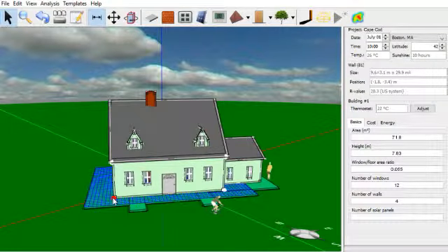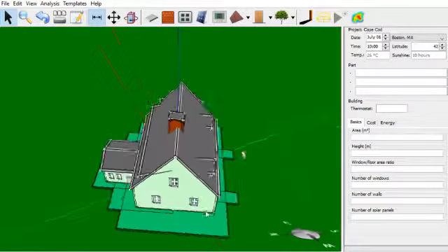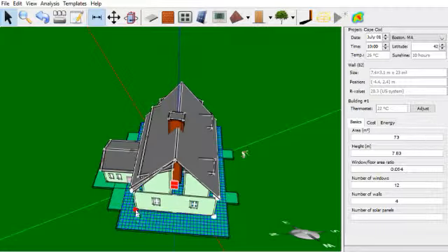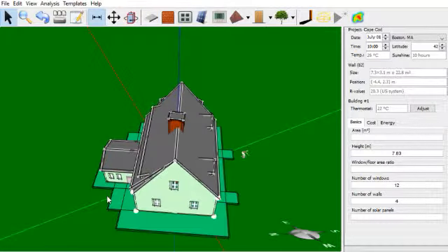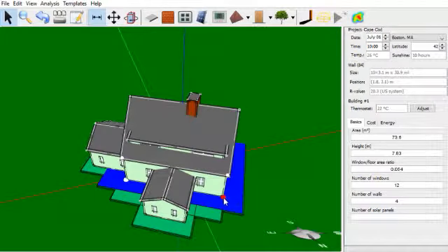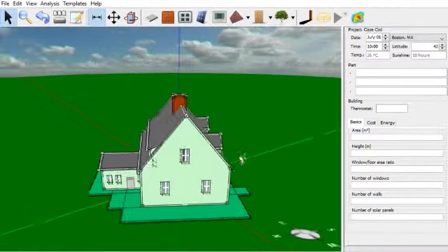However, we can adjust it to be exact by clicking on the wall and dragging the bottom circular node while holding down the Shift key to move it 1/10 of a meter at a time. The roof and home may become distorted, but as you adjust the other walls to match the new dimensions, everything will snap into place. And there you have it.